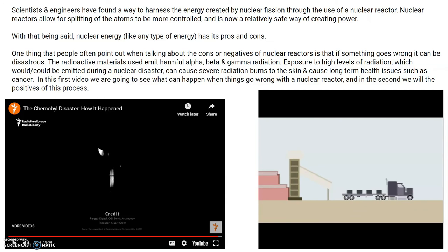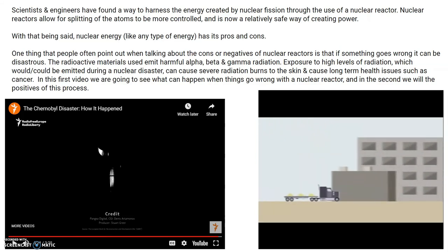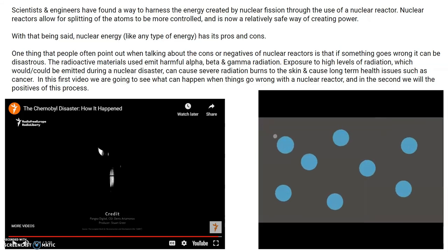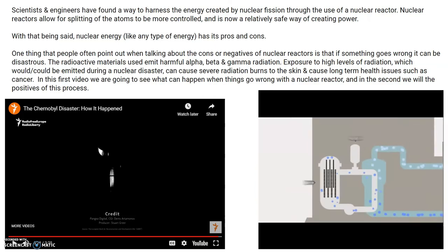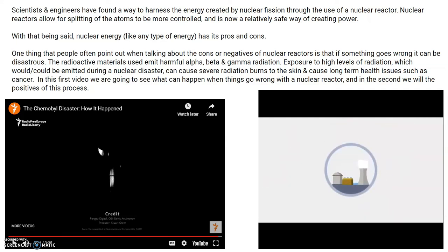First, you have the fuel, usually uranium, which must be mined, enriched, and then formed into pellets that are placed in rods within the reactor. The atoms of uranium undergo a controlled chain reaction which emits heat. Pressurized water around the reactor vessel is heated and circulated through pipes in a steam generator, which produces water vapor that spins a turbine attached to a generator. After leaving the turbine, the steam is condensed so that the cycle can continue.